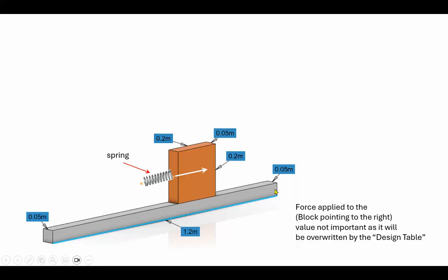The way I'm going to solve this problem is a block sitting on the ground, and we're going to put a spring between a point on the block and a fixed point here. I'll create a point here, which the spring is supported between this point and the point on the block. These dimensions are only used if you want to repeat this and have a record of what dimensions are used. What these dimensions are is kind of irrelevant. However, I'll be using these numbers.